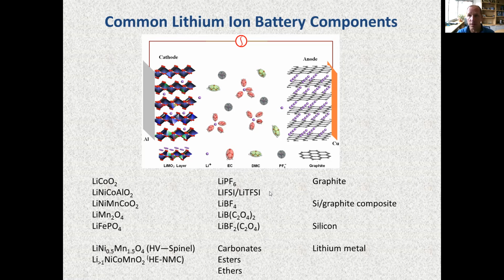We'll go over some of these salts later. These are two of the more promising salts right now within the battery community. However, both of them have challenges and issues compared to LiPF6. Some of the older salts that have been investigated for long periods of time include LiBF4. LiBF4 is also an interesting salt. It has some advantages for high voltage applications, but it also has some problems associated with conductivity. Also, it has some problems with low temperature performance and more resistive interfaces.